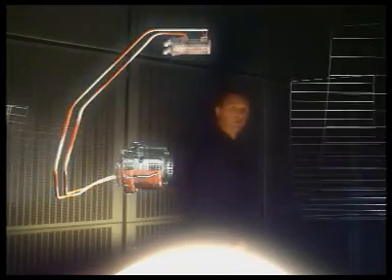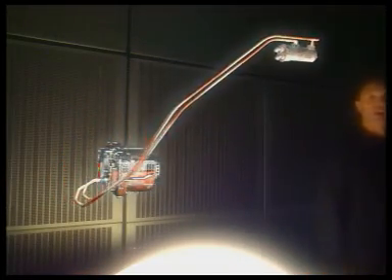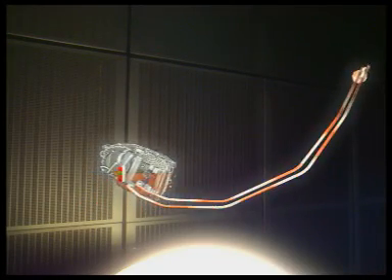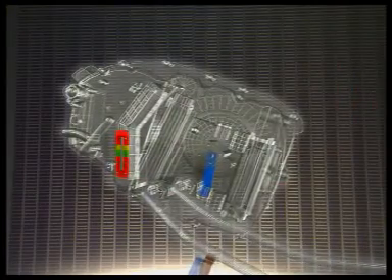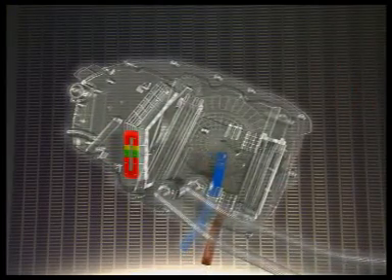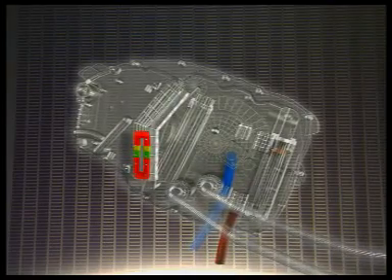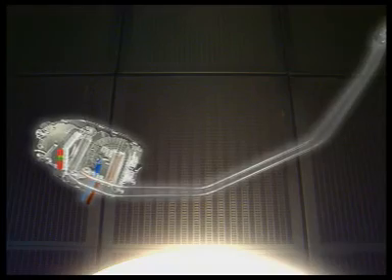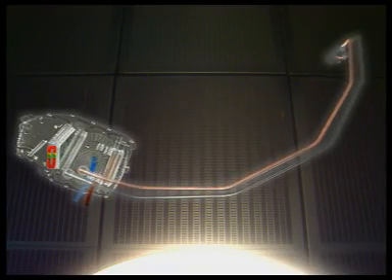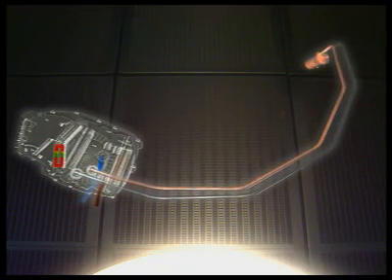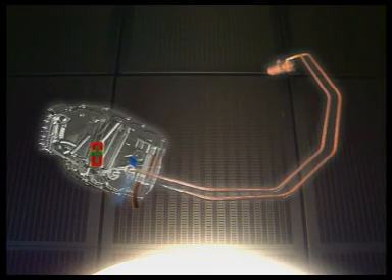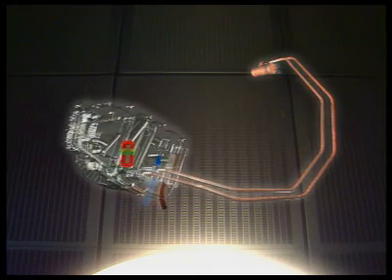During operation, the oil is pumped out of the IDG to be cooled down in the cooler. Then the cooled oil comes back into the IDG. During servicing, the oil is pumped through the IDG pressure fill port. It goes through the IDG filter and exits the IDG into the external circuit, flows through the external circuit, circulates into the cooler, flows through the external circuit, and comes back into the IDG case.